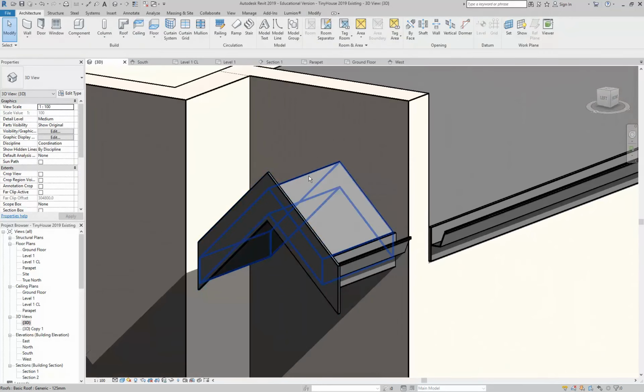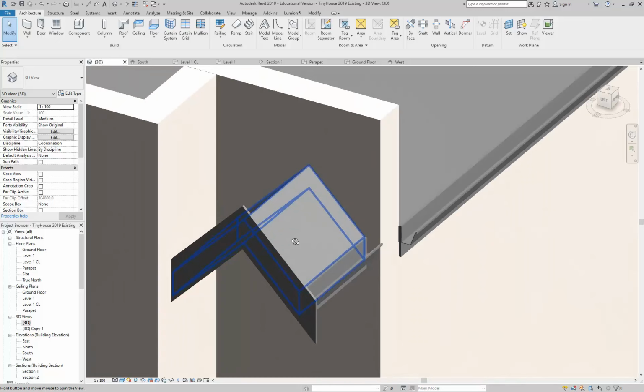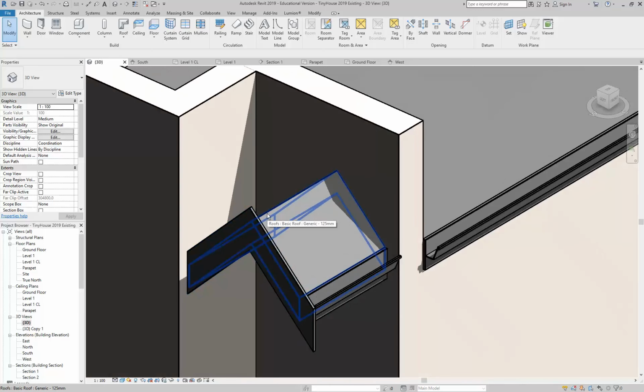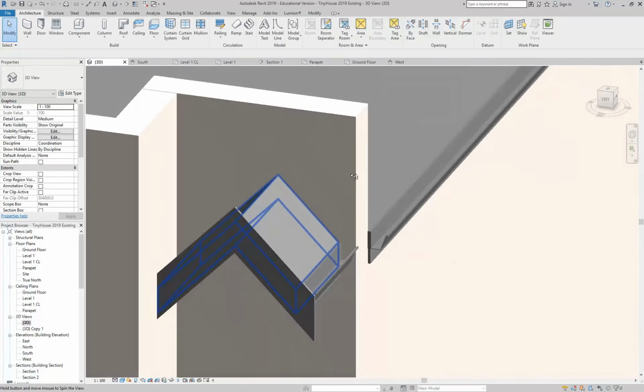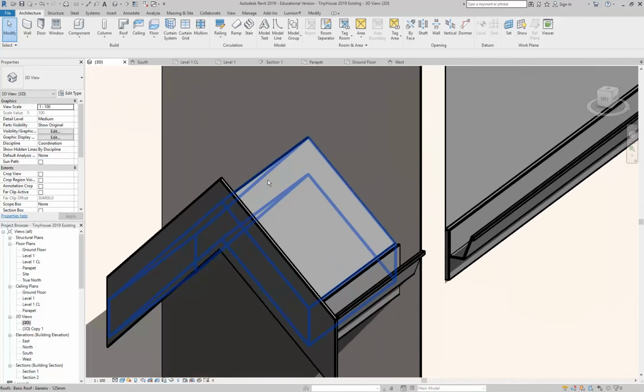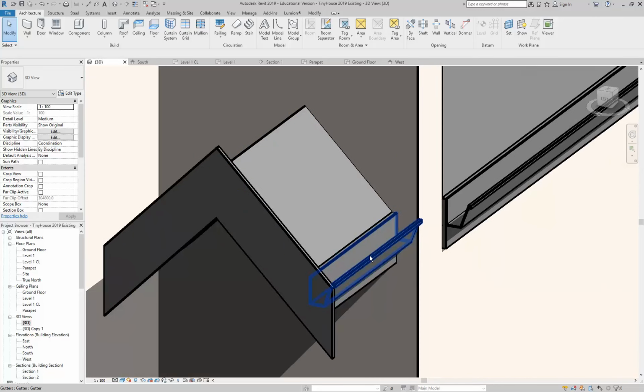The problem with Revit is that they don't want you to model the roof sheeting. You can model it, there are tools for that, but you don't normally need to, because you'll see later you can set a material that's still flat, but it's going to look like roof sheeting, and you just live with the fact that it's not going to be as deep as the gutter, or you can lower the gutter, that's the other option.